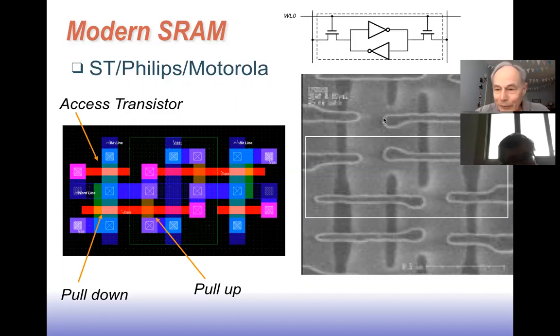This is what it looks like after it gets fabricated. You can see all these nice sharp edges on the rectangles get kind of smoothed out, right? Because this is all very fine geometry, fine processing, right? So it barely works, but it just works. We get enough of a width here to actually make a real transistor. Okay, so that's kind of how it works out in the layout.